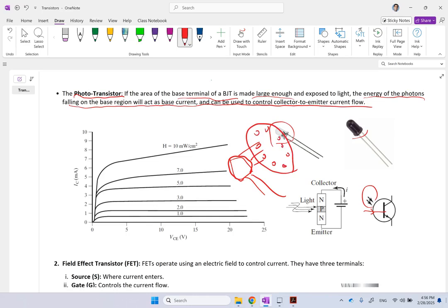So every time the hole comes between the phototransistor and the LED, it allows this light to get to the phototransistor. So the phototransistor turns on the switch, so it will record a pulse in the circuit, whatever circuit it is, correct? And then when the next hole comes in, again, it does another pulse. So you are going to get a train of pulses, each pulse per one of these holes.